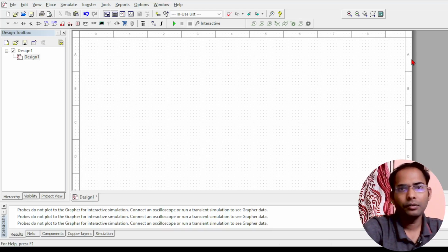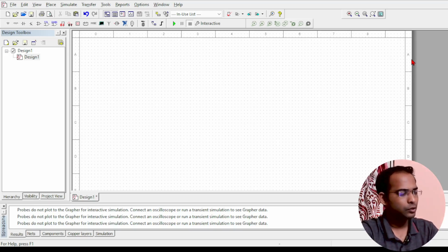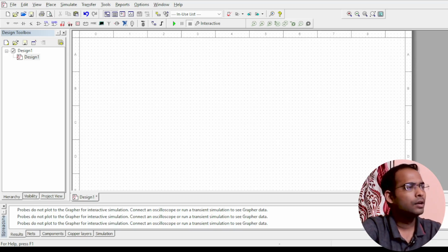Today in this video, we'll see how you can implement your logic gates using Multisim. If you look at logic gates, ideally in what ICs do we have? If you want to use a NAND gate, then I have 7400 that is available in the market. If you do any hardware, then these IC numbers will be required, like 7400, 7402, 7404, 7408, or 7486 for all the gates. But we can use these ICs in your Multisim, or else you will use whatever generic is available there.